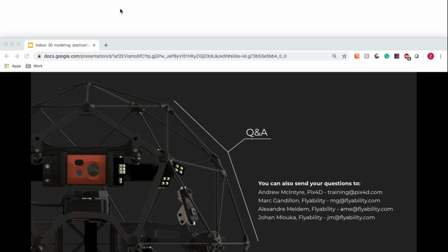The variables to consider are, for example, the geographic size of the project area relative to the size of the constraint, how accurate your results need to be, and how clearly you can identify each of the points in your images. So my rule of thumb is that I will try to always incorporate at least 2 constraints. And if I can't incorporate 2 constraints, then I can at least have 2 known dimensions, and I use one to scale and the other one to check how accurately the project has been scaled.